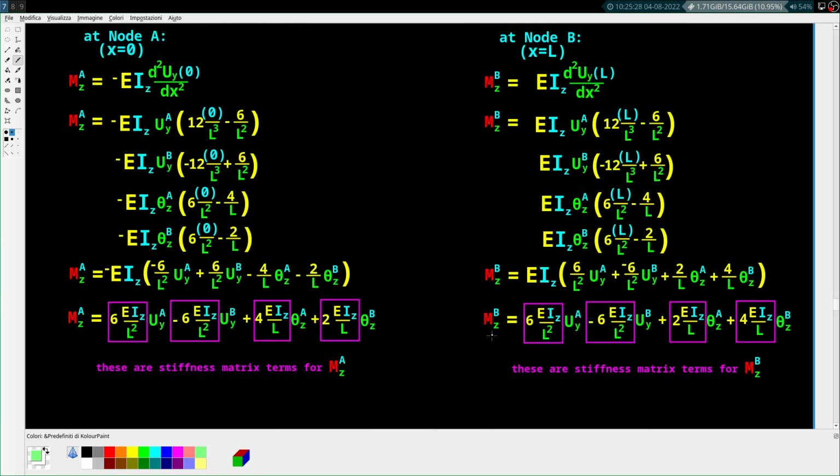And so basically, that means this sign has to match this sign. And it does. If it didn't match, you'd put a negative sign here. Who needs definitions and concavity and all this garbage and keeping track? Just make it make sense. On the left-hand side, you need the moment at A to be positive and the rotation at A to be positive. If not, you put a negative sign in front. And here we had to, right? And so that's why this comes out.